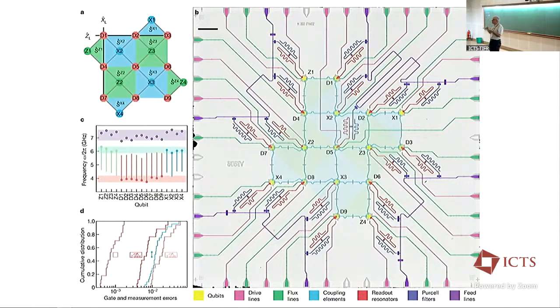That is, you send electromagnetic signals into this device. They enter via these transmission lines, and they reach some point, and then they do something. And so these many, many contacts, or the edges, are the places where these signals come in or out from the outside world. And then all of this is described by some electromagnetic dynamics. And in fact, almost all of it can be described with linear dynamics, and that's what I'll write. My first few equations will be emphasizing that point. The big exception being the Josephson junctions.